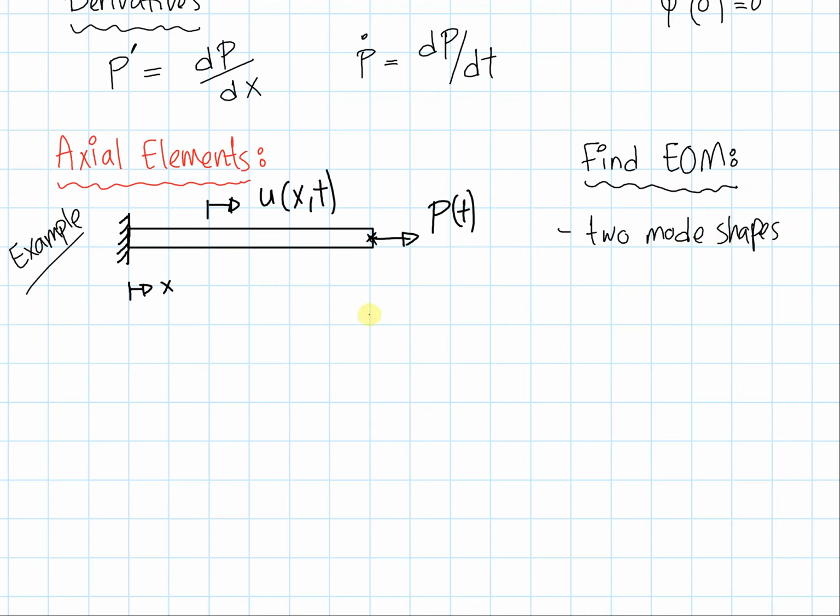And so I first need to identify what my boundary conditions are, and there's really just one. Psi 0 is equal to 0. So I have no deformations at the base. And having said that, I'm going to introduce two shape functions that satisfy this boundary condition, and ones that I think are suitable for this problem.